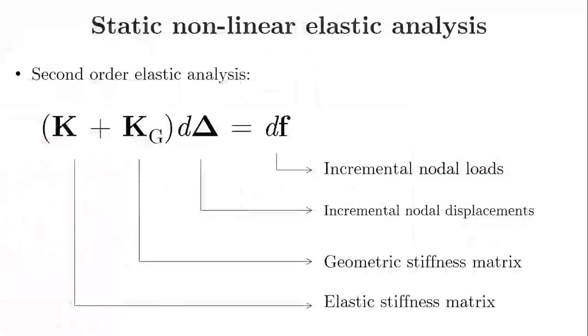The third type of analysis treated here in this work is static nonlinear elastic analysis. In a geometric nonlinear analysis, the deformed configuration of the structure must be taken into account when solving the equilibrium equation. For that, iterative methods that update the deformed configuration and, by consequence, the internal force and stiffness matrix need to be implemented.